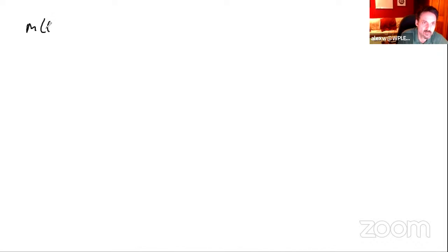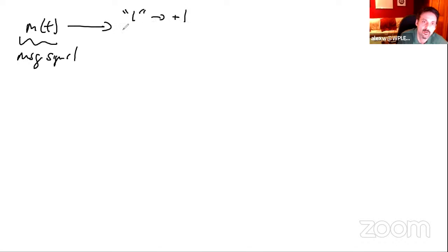Your m(t), this is your message signal, not text message signal. What you do is your binary 1 gets mapped to an amplitude value of +1. Your binary 0 gets mapped to an amplitude value of -1. Keep that in mind. Step 1, right? Now if you have a binary sequence,